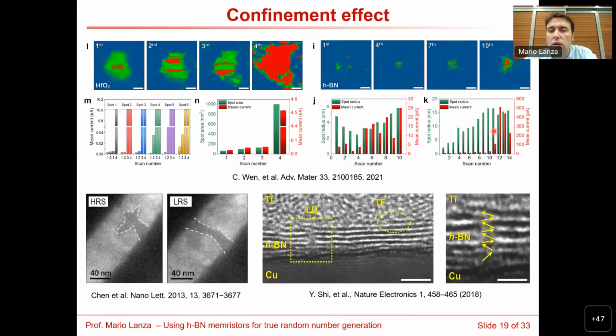We have done one experiment in the boron nitride that is very interesting. We scan the surface of the boron nitride with a conductive atomic force microscope, and we observe several spots of the sample that are more conductive than others. These spots of the sample are these lattice distortions. This point will be this point, the green and red one. And it shows higher electrical current.